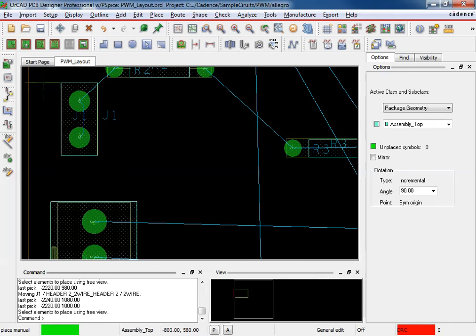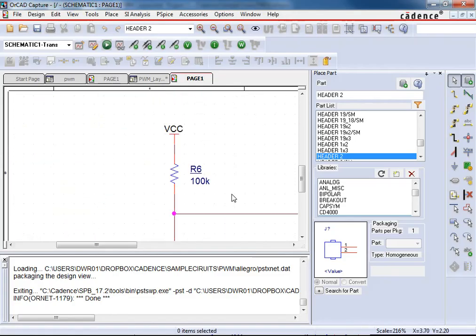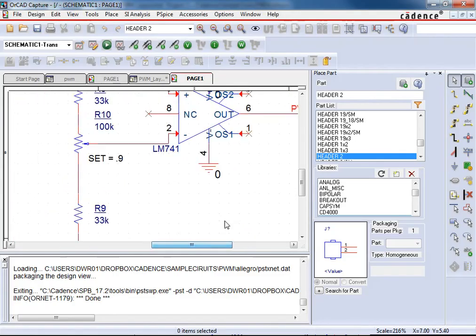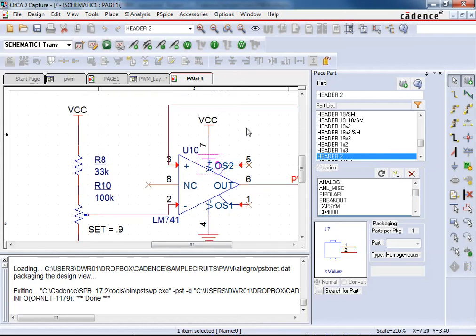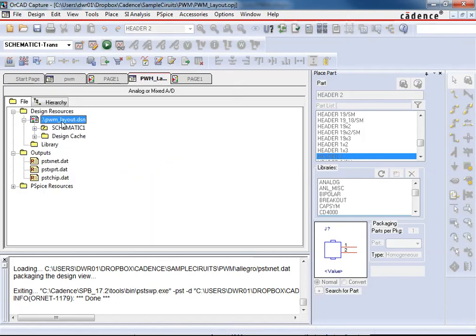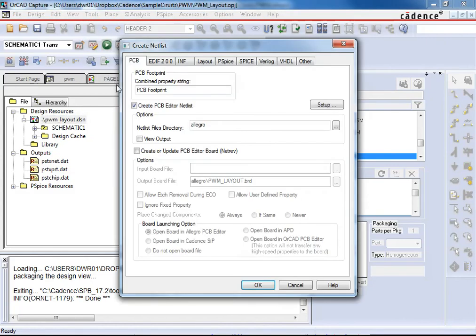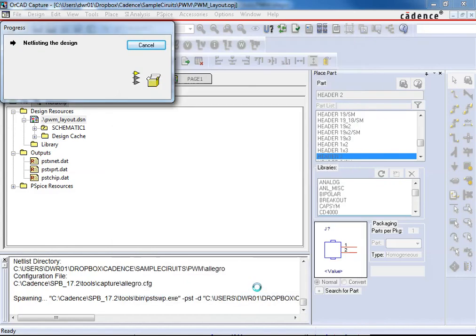So hold on one second, I'll pause the video. Okay, I found where my mistake is, and I'll show you how to fix it here. Notice I've got a ground here tied to VCC, so ground was connected to VCC, so that's where the problem was. That was a mistake that I hadn't noticed. Now, it's not the end of the world. Once I deleted that ground, I need to go to create Netlist again, and then I create a new Netlist,